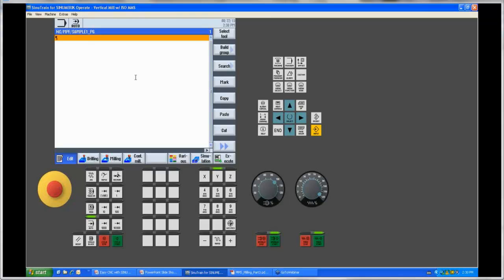So first step, just like a very traditional G-code program, I'm probably going to want to tell the machine that I'm in an absolute mode, what work coordinate I might be using. If I'm in inch-metric mode, this will be our inch statement, G70 for our protocol, and what native orientation my tool is in. The next step I commonly do is define what the workpiece looks like. That would be my blank. Now normally that's set up in the header of ShopMill. Here we have an individual function under various called blank.